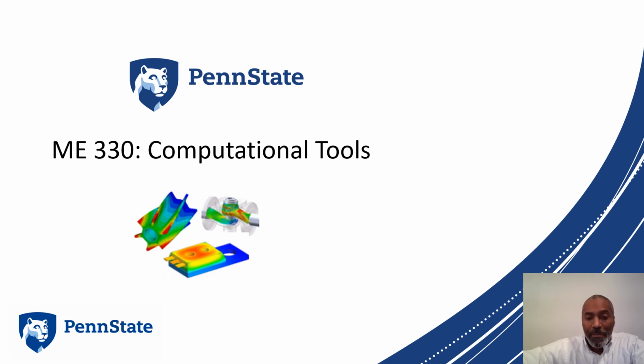Well, thank you for participating. Hopefully you've learned a little bit about the comparison between solid elements and beam elements, and you have an idea of when to choose one versus the other, what sort of geometries are amenable to long, slender approximations for beams, and what would be better suited by solid elements, and you have an idea of the concept that at times you may need to divide your model into more and more elements to ensure that your solution converges to a value that's closer to what the real solution would be, or closer to an analytical solution if you've got something to compare it to.